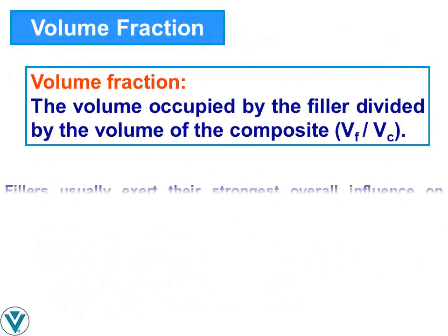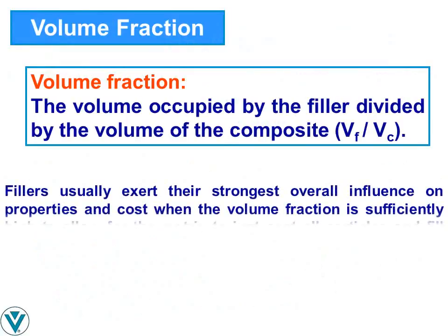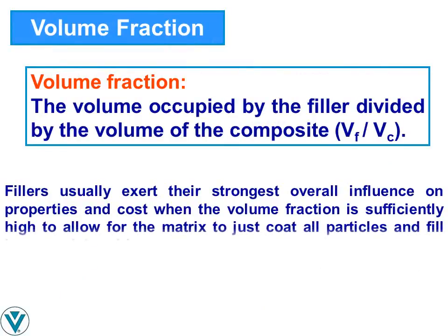Fillers usually exert their strongest overall influence on properties and cost when the volume fraction is sufficiently high to allow for the matrix to just coat all particles and fill interparticle voids.